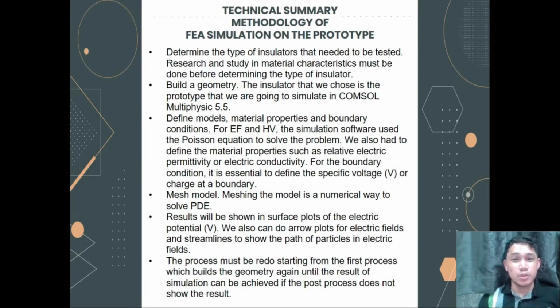Meshing the model is a numerical way to solve partial differential equations. In this process, the geometry is broken into small pieces called elements. Linear behavior can be assumed, and each one of the pieces can transform the entire thing into a system of linear equations, expressed by a matrix, which can be solved by the software to find the best approximate solution to that system of equations. Essentially, by meshing the model, it is transformed into a system of linear equations and can solve the electrical problems. A finer mesh is best to get a more accurate result, but needs more computation time.